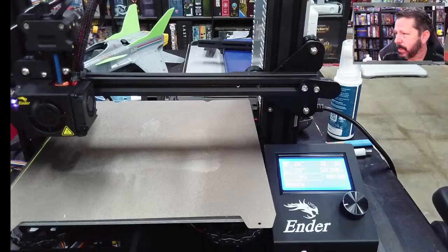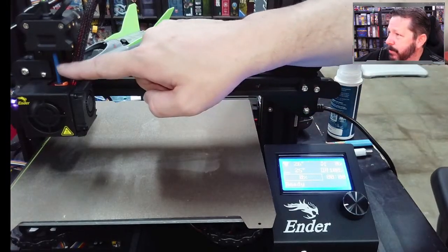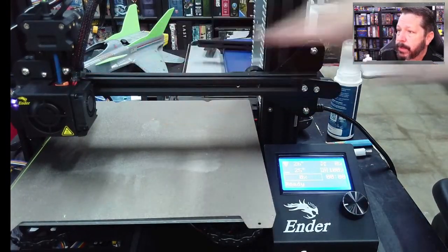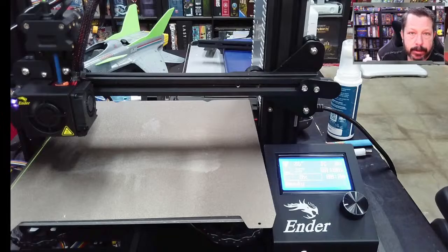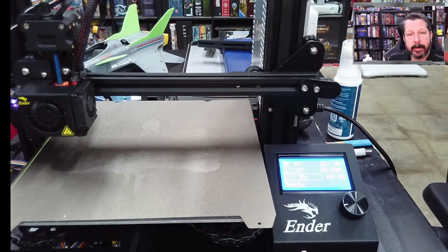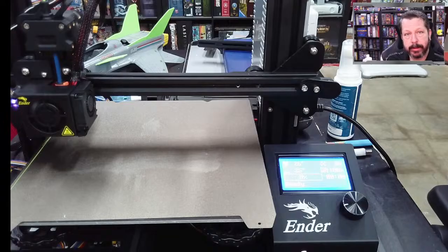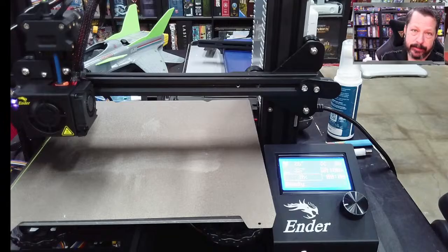For ours, we just have this little short path right here, but for a printer that has the Bowden tube, that might be 20 inches long or something, there's a lot of pressure that could be built up when the feeding mechanism tries to feed filament into the hot end, and then you stop feeding all of a sudden, like you're done with the layer or whatever it is.